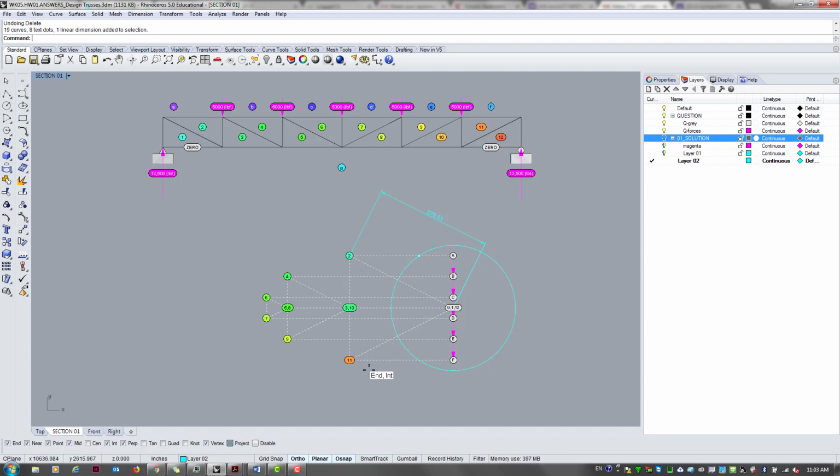Right, so I'll just do it once again. I'm gonna turn the control. Yeah. How do you make the dimension go sideways? Yeah. Okay. So go here and pick the fourth one, which is aligned dimension, or I guess you can also type dim aligned, and that way you can pick whatever point.